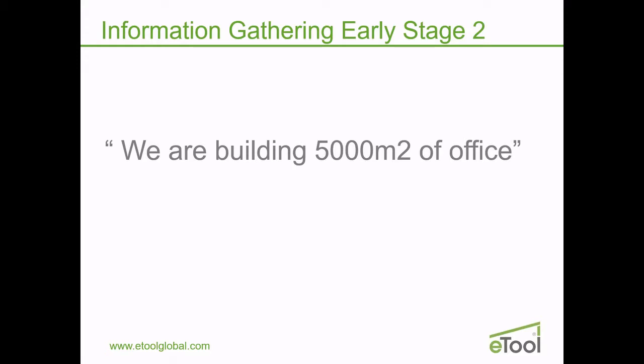We want to have a look at some LCA analysis. We've got this stage 2 requirement for BREEAM, so let's get stuck in as early as possible and see what we can get from an LCA model with that level of information. And we'll come later on at stage 4 and update it and build a more accurate LCA of the project. But for the time being, all we know is that they're building 5,000 meters squared of office. It's probably going to be concrete for that size office, but it might be steel, it might be curtain walling, it might be brick facade.